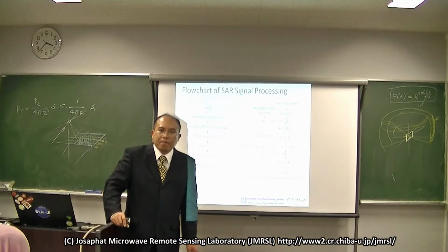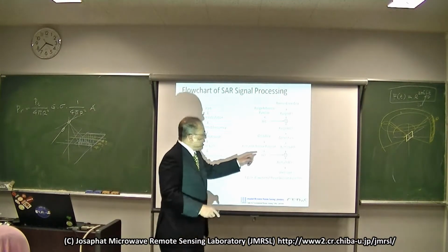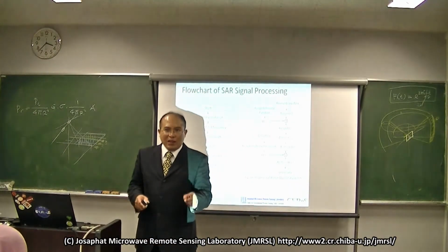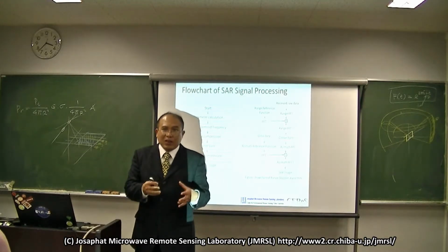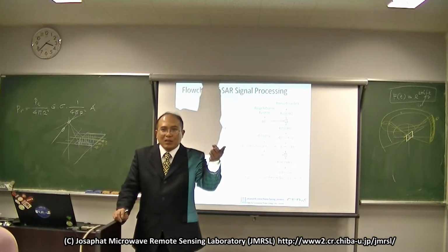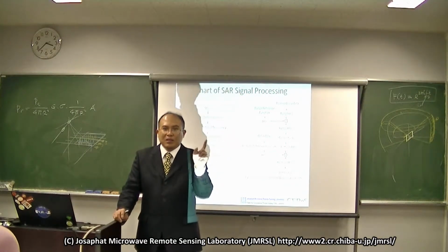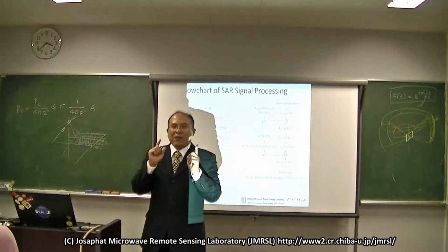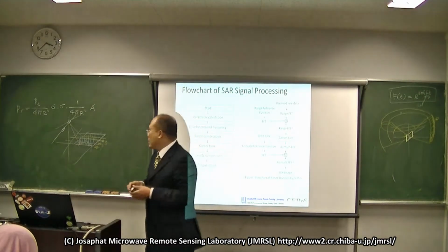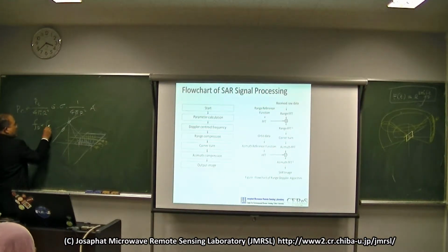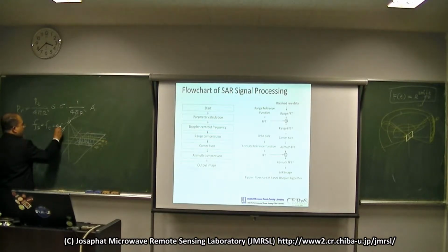Range Doppler and the Doppler center are not the same. Okay, later, yeah. I thought the center frequency is used here, but actually, because of the effect of the velocity of our Earth, or if you want to launch to a different planet, you must consider the velocity of the planet. Yeah? So in this case, you must consider the relative frequency. So in this case, the Doppler frequency is the center plus some delta f, plus minus.